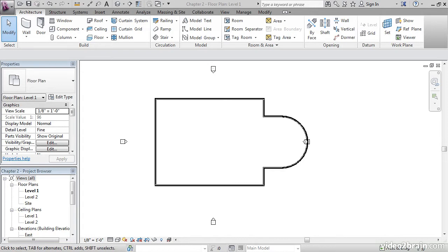We're going to mirror two walls to allow us to keep modeling. Once we have the items mirrored, this will allow us to continue to fill in the gaps with a radial wall. This exercise will focus on the object selection process, the process for mirroring, and to practice moving ahead with modeling a radial wall based on 3 points.